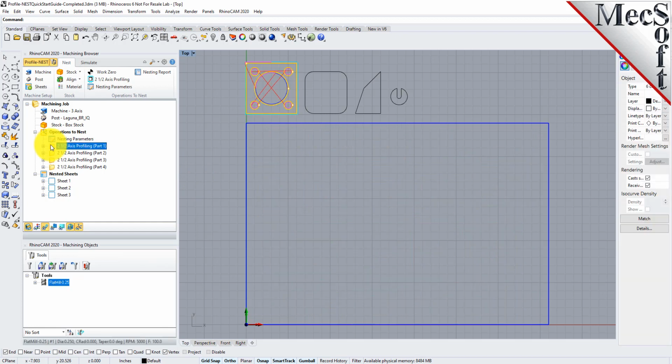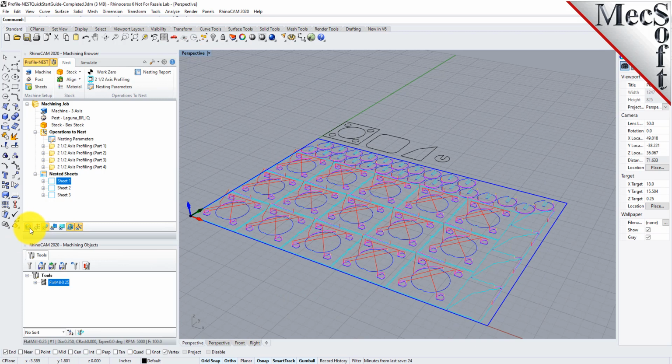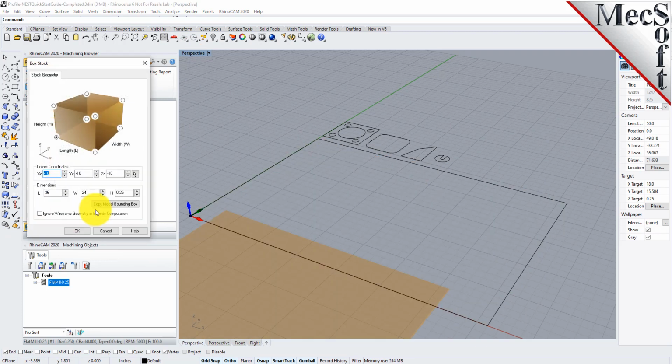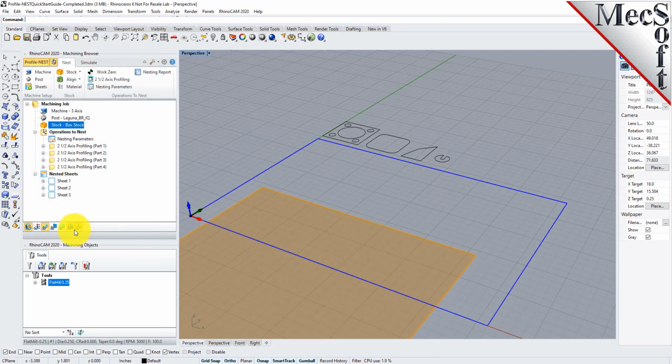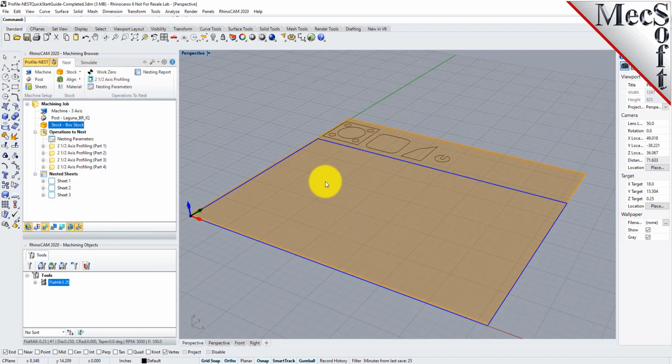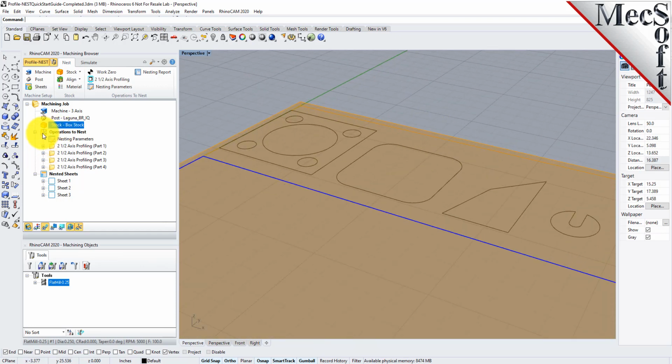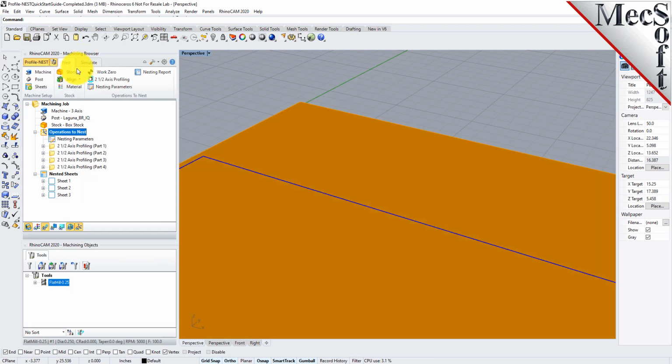Okay, so I was mentioning that you can perform a cut material simulation on either your source profiles or your nested profiles. Let's do our source profiles first. Since we don't have any stock coming up there, let's change the dimensions of our stock to go up that high, so it extends up and we can see a good view of the cut material simulation. Let's go to isometric view and do a simulation. Let's slow that down just a bit and pick play.